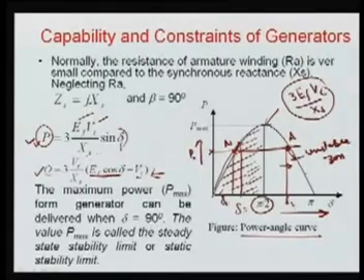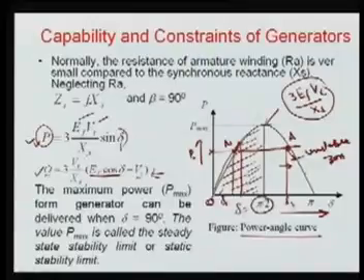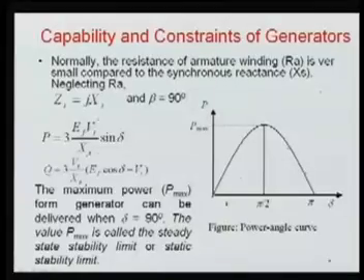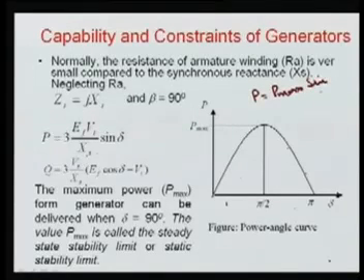So only the sign depends upon here. However, this power is every time positive because that angle always starts from 0 to delta, that is pi by 2. So it depends on whether this Q is negative or positive, and it also tells whether it is overexcited or underexcited. So in this expression, the real power P, I can now write in terms of P max sine delta.